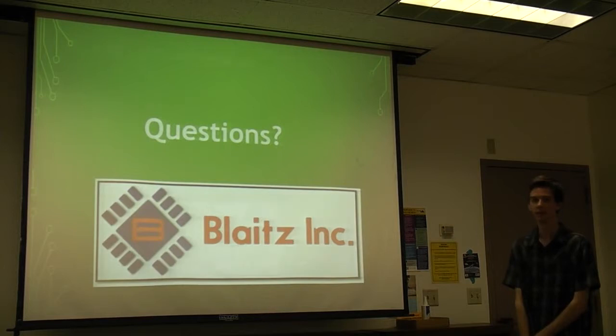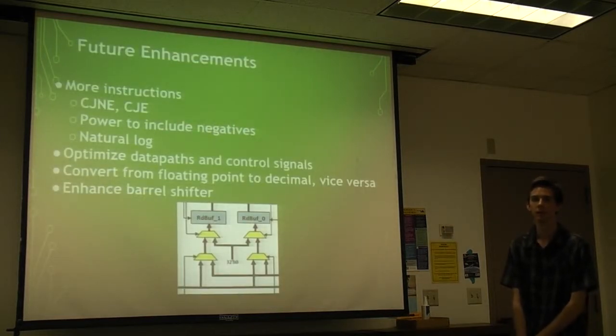The compare and jump if equal, you said you don't have much range, but let's see, 18 bits are used for the 2 registers and an opcode. Doesn't that leave you 14 bits? Well, we thought we would have to add new control signals. We would like a larger range. 14 bits is not enough. We were trying to implement it and we ran into some problems. What's ARM's range on their conditional jumps?